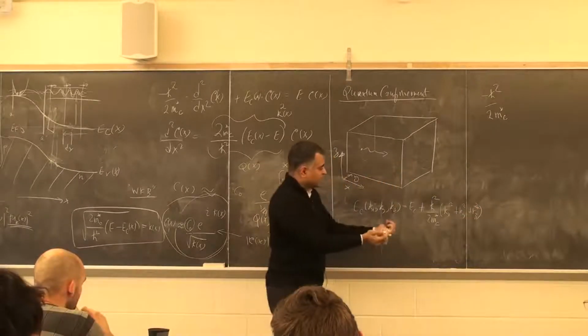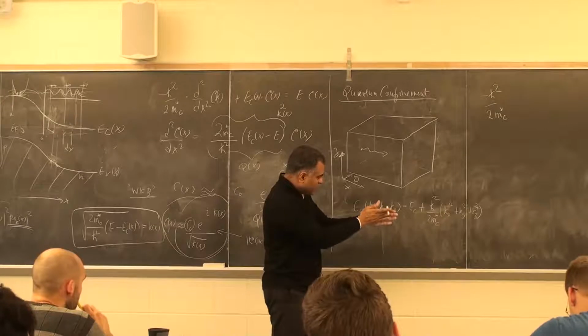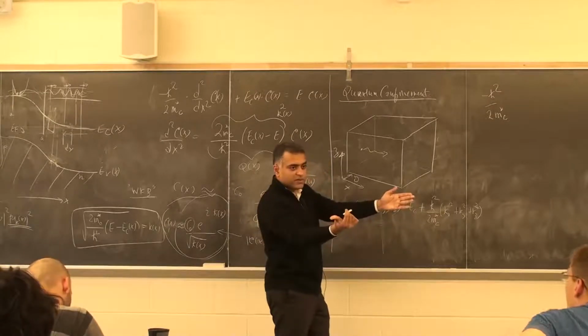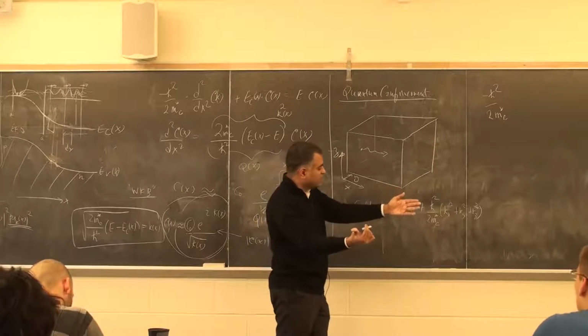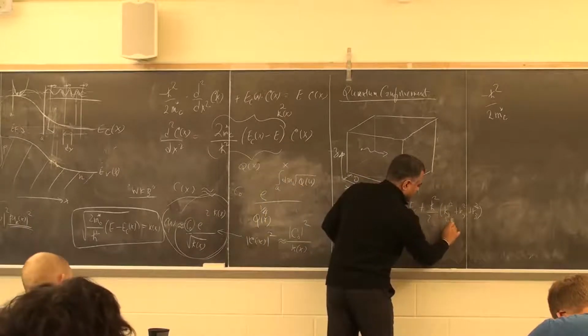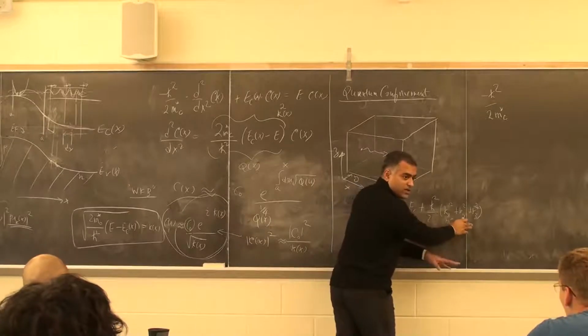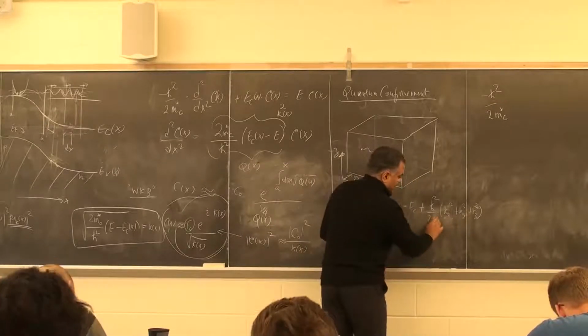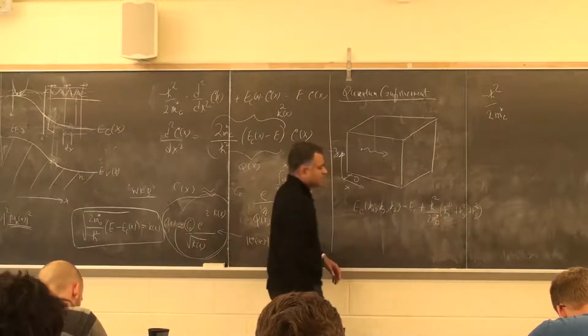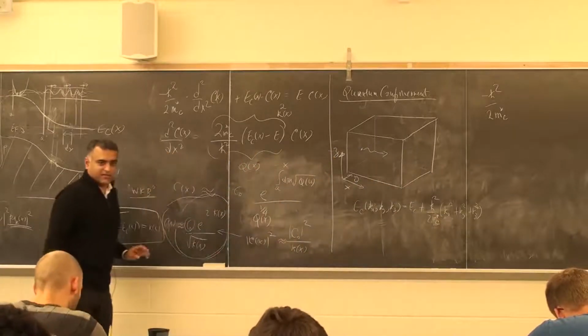So in silicon, for example, if you go along the 1, 0, 0 direction, the effective mass is larger than if you go along the perpendicular, transverse direction. So in which case you must actually have m star xx and yy and all that. So I'm not getting into those complications. Effective mass is indeed a tensor, but let's neglect that for now.